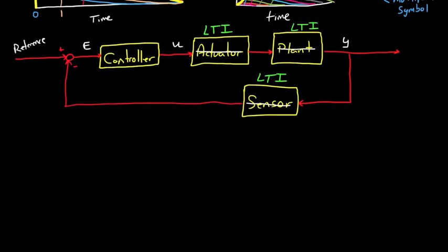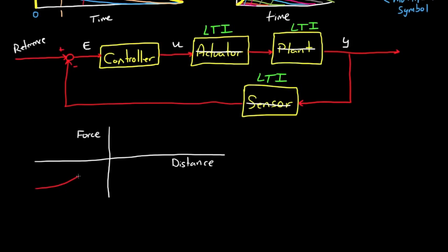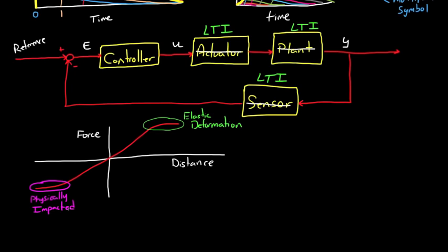Let me leave you with a common example of a nonlinear spring. If you plotted a real spring's stretched length versus its restoring force, it would most likely have a shape similar to this. When you stretch it too far, eventually the material will give and start to deform plastically. If you compress it too far, the coils will start bunching up and physically impact each other.